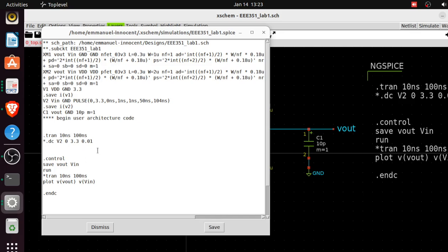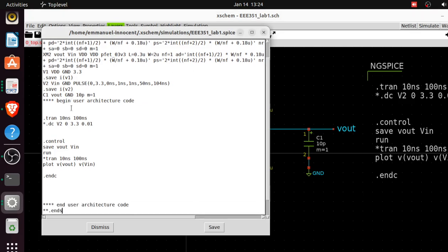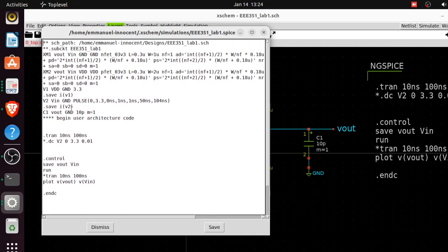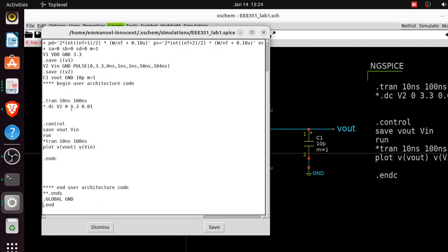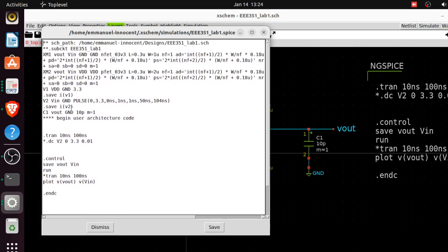spice directive here. When we click the netlist, it gives us the full netlist, so we can see everything. The advantage of this is when you get to understand the spice language, you'll be able to go through it yourself and confirm that everything works well. Sometimes if there's any error with the graphical schematic you've made, it won't even show anything. It will tell you that there's an error, and that way you know. So that's the advantage of generating the netlist.